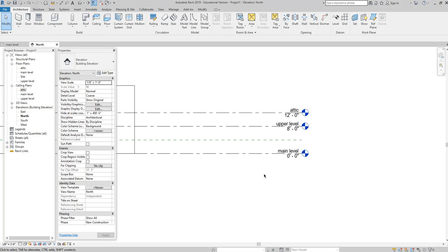These are really important, and when you're first using Revit, it's kind of hard to recognize, but the second you complete a full project, levels are probably one of the most important things to specify correctly at the start of your project, more so than wall types or window types or anything like that. The first couple projects you do, it'll be iffy, but then you'll get a really good hang of it, and they're pretty important to get right the first time. Not to scare you, but you want to pay attention to these levels.